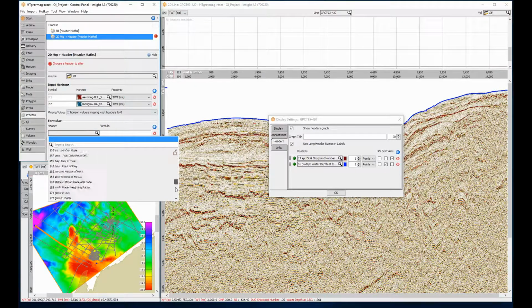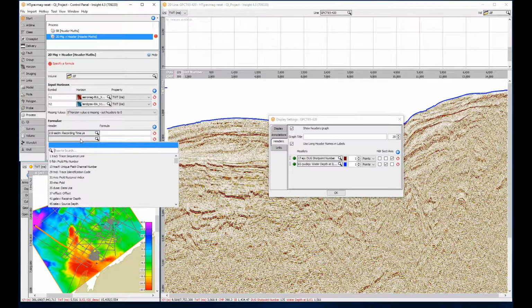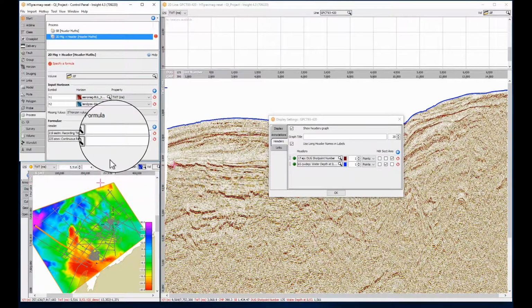Here I will select bytes 219 and 225, which I know are 32-bit integer values and not used for this volume. The attributes can be scaled and shifted using a simple formula to emphasize and position them close to a feature of interest, such as the basement.